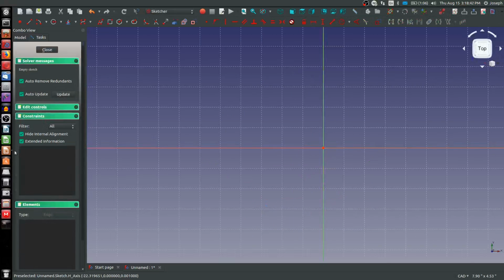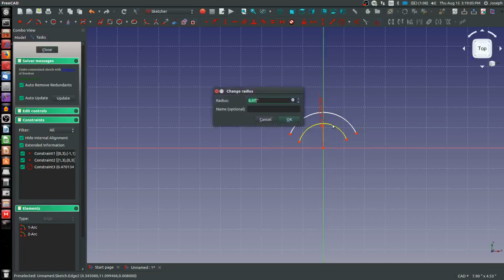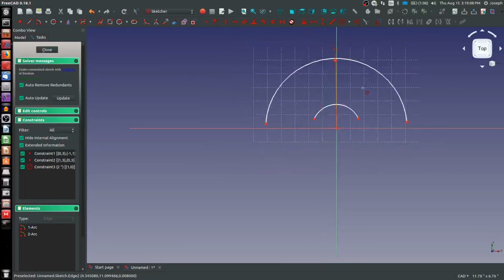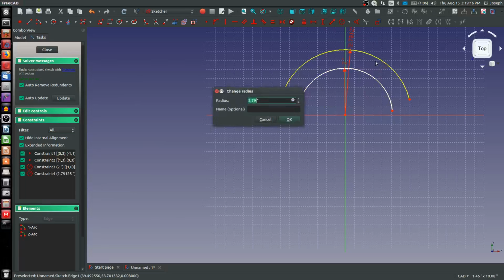With the sketch being created, I want to first, and this is rather arbitrary where I'm going to put my origin, but let's create two arcs, and I'm going to dimension the inner radius to 2 inches using Shift R, and I can give this a thickness, at least arbitrarily, with Shift R again. Let's make this 0.375 inches thick, so 2.375.